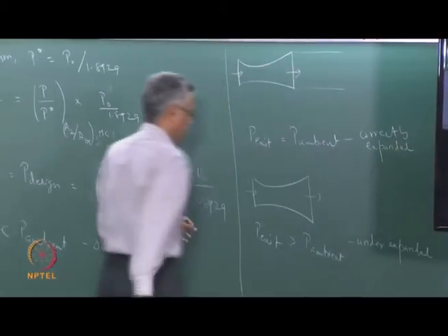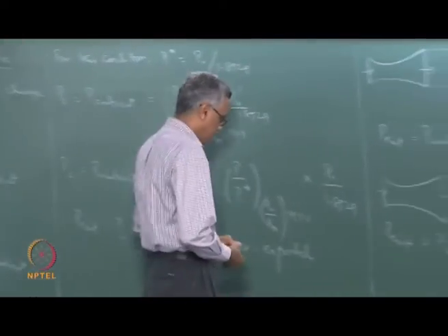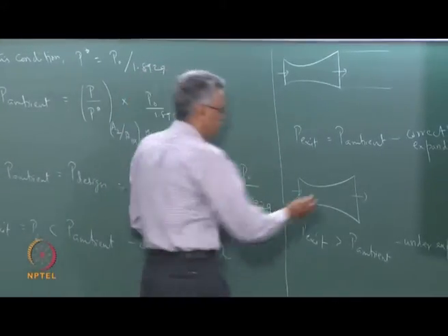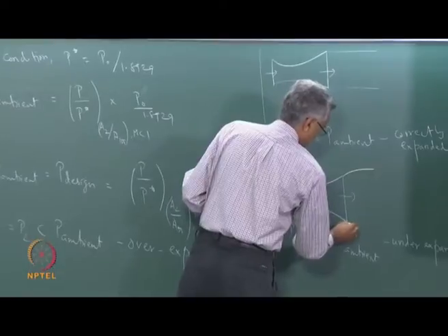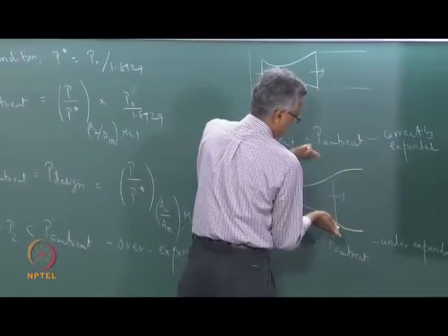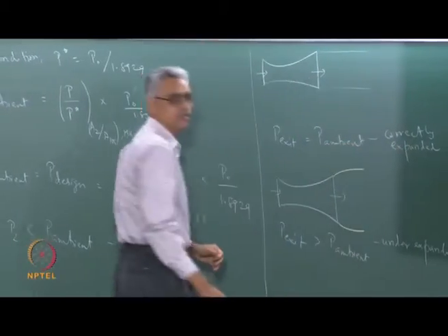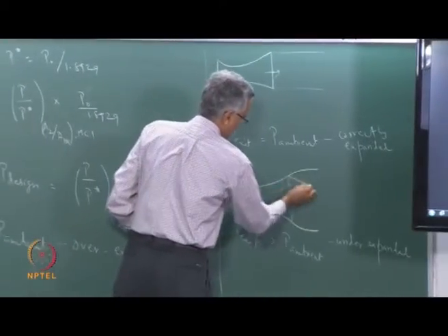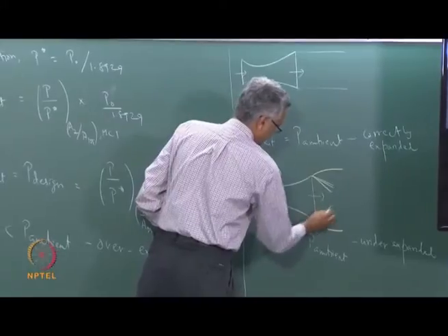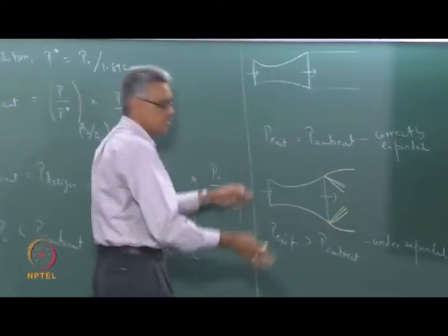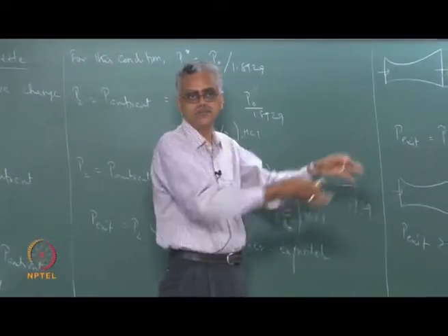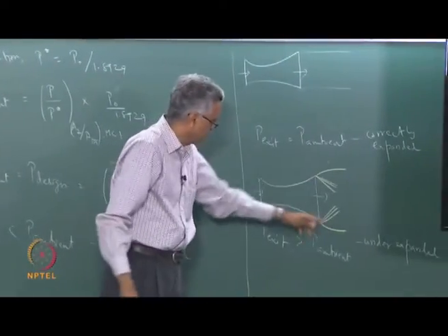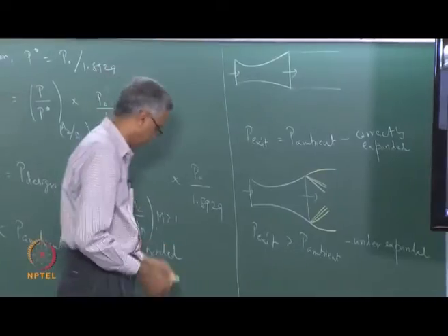If this happens, then as we said earlier, the jet swells when it comes out. It initially swells like this and then it will equilibrate and keep going like that. Normally what happens is you get a sequence of expansion fans here which expands the flow as it comes out and then tries to equilibrate it with the ambient. That is why the diameter of the jet becomes larger than the exit diameter.